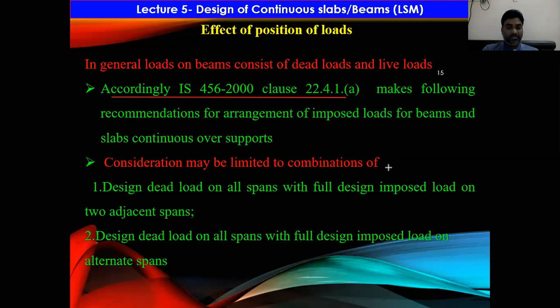may be limited to combinations of, the first one, design dead load on all spans with full design imposed load on two adjacent spans. That is the first case. And the second point, design dead load on all spans with full design imposed load on alternate spans. That means the first case is design dead load on all spans with full design imposed load on two adjacent spans.